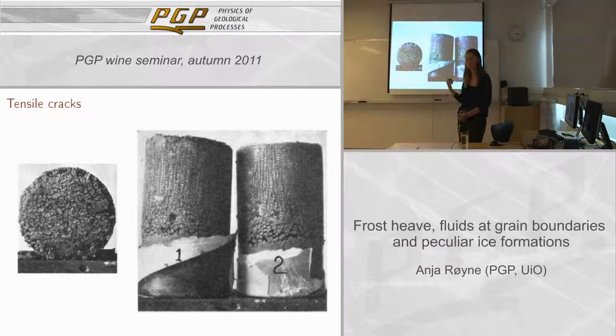And then he calculated that in his experiments, some of these pressures would be equal to lifting up water to a height of 15 meters. So to do that, you need very high negative pressures, and maybe at some point the negative pressure would be so negative that you would start boiling the water, and then you would break this liquid film, and that would stop frost heaving.